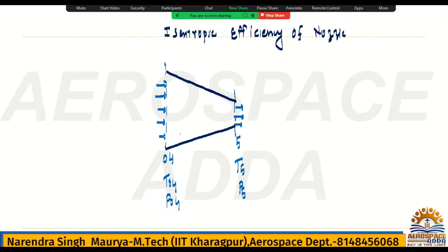All right, now the isentropic efficiency of the nozzle will be denoted by eta n. Now what is the isentropic efficiency of the nozzle? As I mentioned, the diffuser is basically used to convert kinetic energy into pressure rise, so there will be a rise of enthalpy, or you can say temperature. But the turbine and nozzle both try to accelerate the flow, so in both cases there will be a fall of enthalpy or fall of temperature.